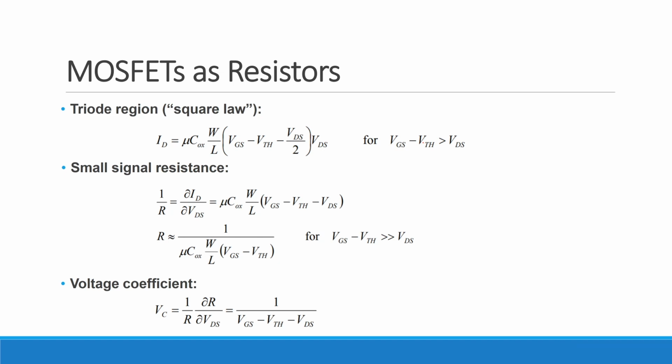We said we can get maybe somewhere like 100 to maybe a kilo ohm per square. If you really want really, really big resistors, that obviously gets big quickly. Like let's say you wanted, I don't know, a gigaohm or something like that. That gets painful. So in some applications, you will actually end up just using a MOSFET as a resistor. And the way you do that, in case it's not obvious, is basically just put some relatively high VGS on the device so that you make sure it always operates in the linear region, right?